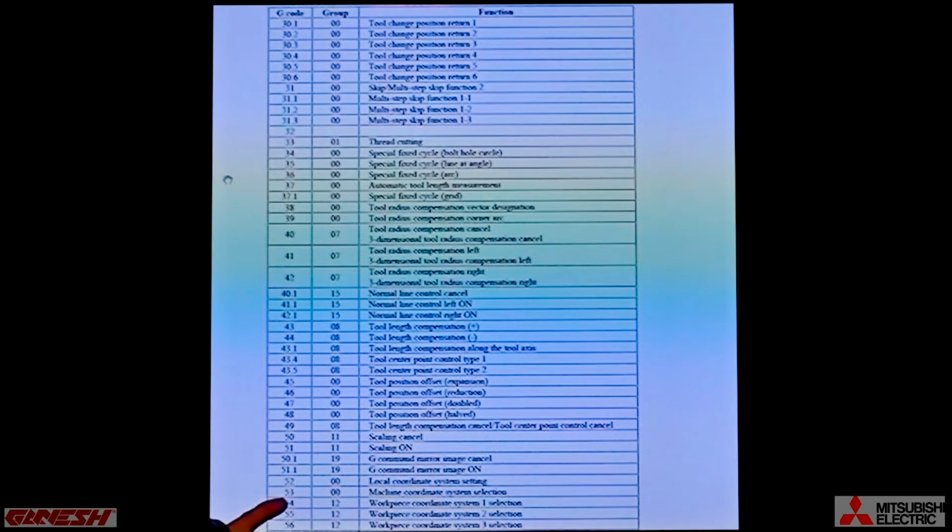And then here's our working planes, G54, 55, 56, or rather our workpiece coordinate systems. Those are worth remembering, okay? Those are relevant to which coordinate system you're at, especially if you're on a horizontal mill, where there'll be multiple workpieces chucked up on a tombstone. You'll want to use plenty of these work coordinate systems.